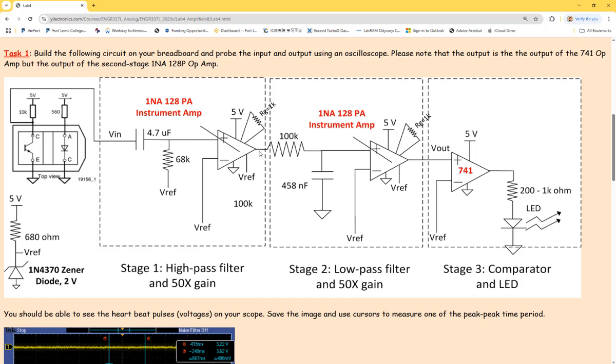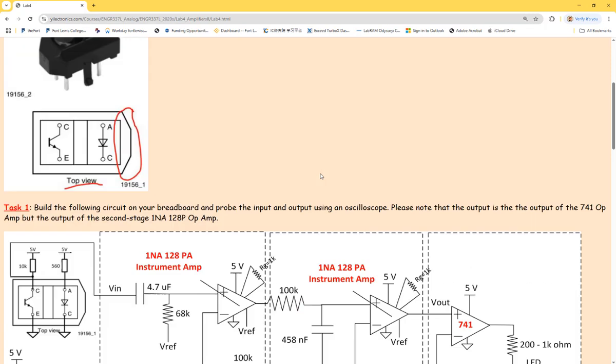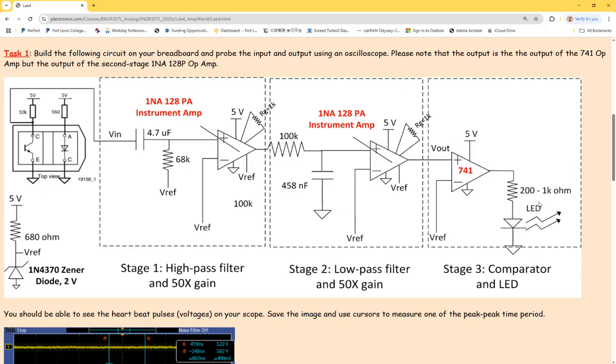Okay, so I'm going to give you some options for the analog sensors for you guys to use, and I'll give you the circuit to start with. And you can modify the resistor and capacitor values to change the cutoff frequency for the filters, and eventually output a reliable analog voltage, which is detectable by the ADC you have for the FPGA.